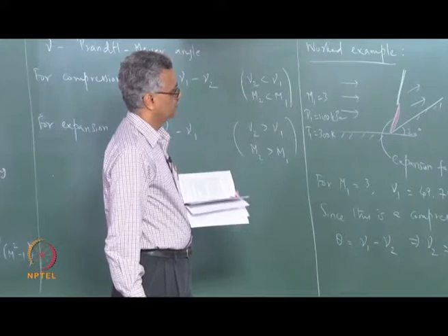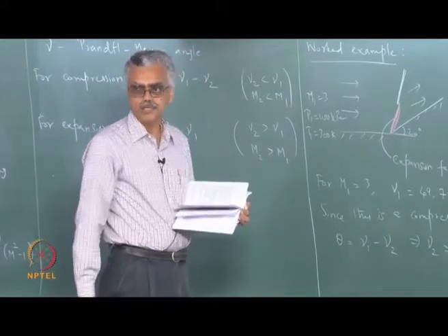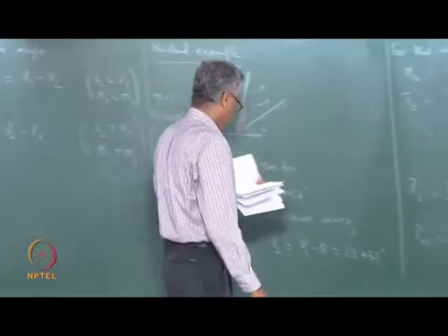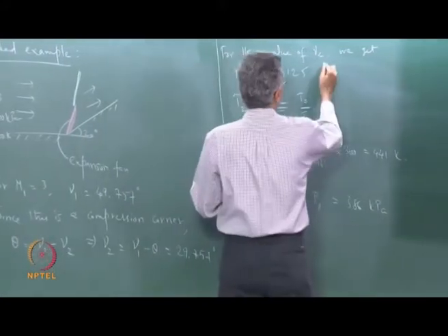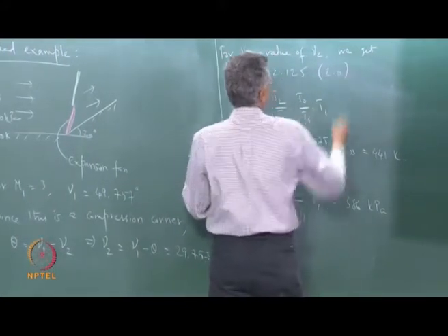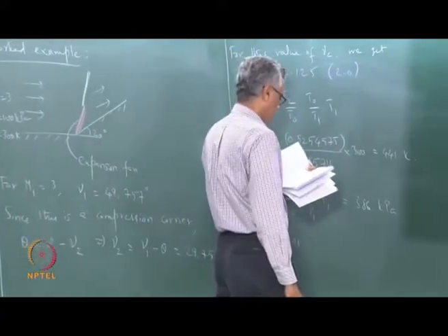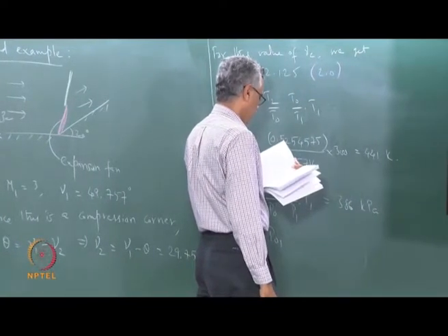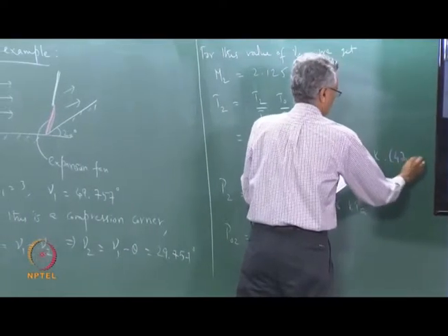So the same shock, had it been through an oblique shock, we worked out this example in the previous chapter. So had this been an oblique shock, the corresponding numbers would look like this. The Mach number for that case comes out to be 2.0, and the static temperature came out to be, let me see, did we calculate that? Yes, 470 Kelvin.